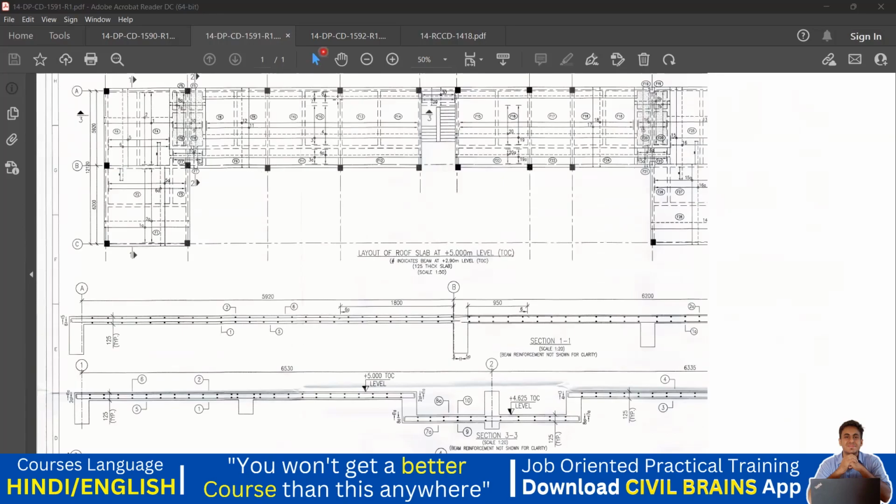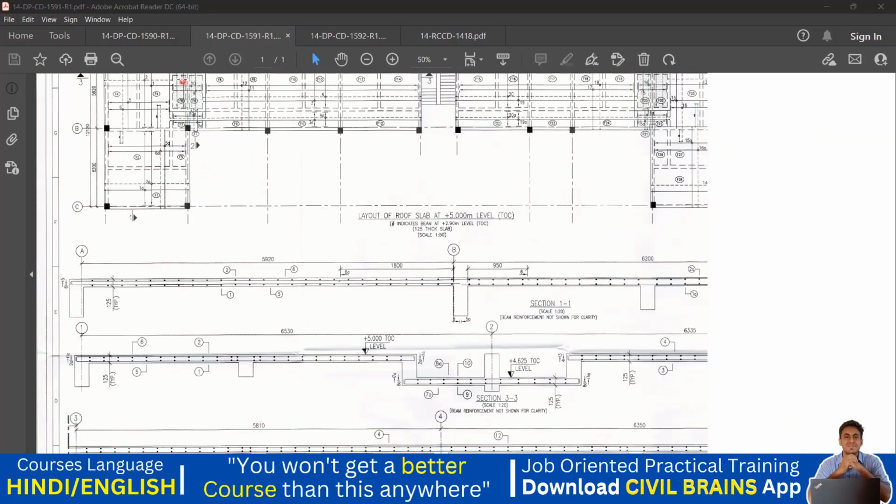We have understood the roof beam layout and roof slab layout. Also the reinforcement details are understood by us. One more thing. See here, whatever reinforcement you can see, everything is a cut reinforcement. It's not a crank bar system. Usually in industrial buildings we don't go with a crank system, like a bent bar. I already explained what we exactly do.